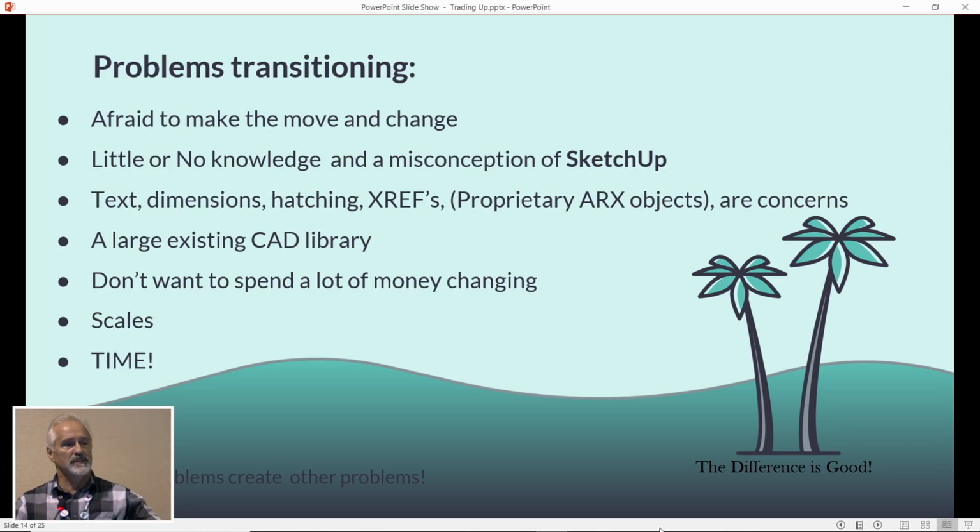You can stretch that dimension. As you stretch that dimension, the dimension text updates. You've seen that in CAD, you've seen that in SketchUp, you've seen that in LayOut. That is an attributed block in a form. Different programs think of it differently, but text can be a problem in a dimension. Dimensions are problems within themselves. Some text styles will not translate into SketchUp. I've seen few, but I've seen enough that I say text definitely sometimes does not translate.